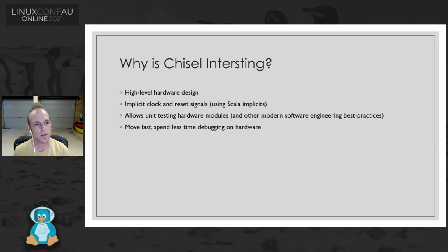So the more time that you can spend writing circuits and verifying them in the same space, not having to make a bitstream and run it out onto an FPGA, that keeps your iteration loop very fast. So this whole red-green refactor mantra you can replicate in hardware land. And for some big designs, synthesizing out to a bitstream for an FPGA can take minutes or hours. So the faster you can keep this loop, the better.